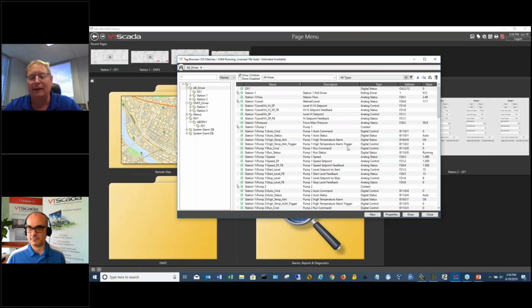In the extreme case, let's say you've got 1 million PLCs. If they're all on a high-speed network, VTScada can handle it internally, but your network might not be able to handle all of that network traffic over an Ethernet network. If you had serial connections, then obviously you're limited there on the bandwidth of your serial connection.